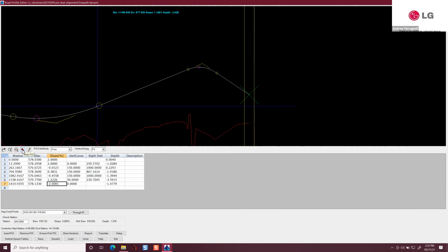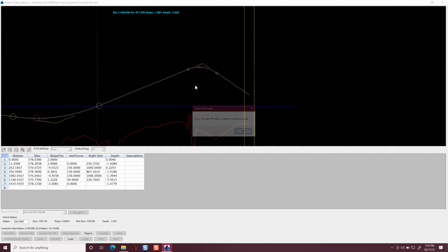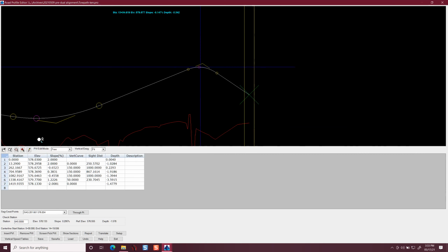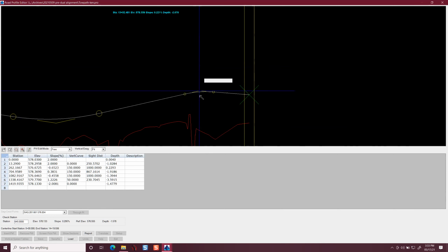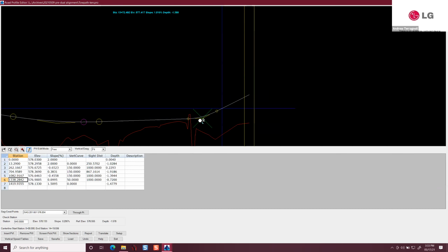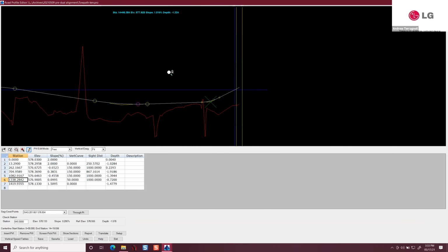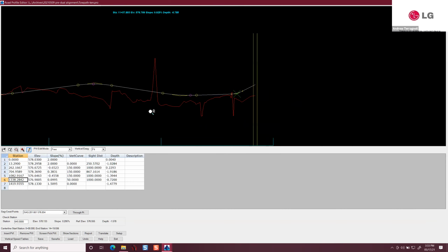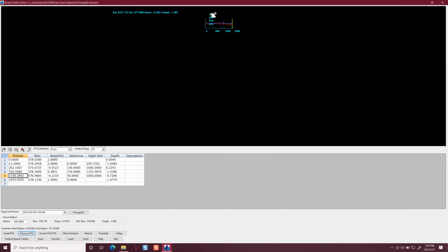So then I would take this as an edit now. I keep getting the wrong button. So I would actually probably pull that down to where this is a slope, as long as I get a half a percent of slope, but it's really flat in there. I'm not going to get too much drainage even in a concrete gutter, so you might even take this one out. I'll just remove that one.